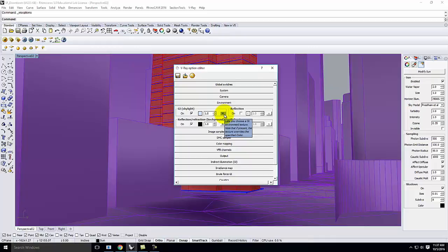And that's because there's a lot of other light that bounces off of the environment that lights the scene besides the sun. So we have the all-powerful sun shining in, but we also have reflected light off of the sky, off of the clouds, off of the trees, whatever. So we need the reflected light, and that's represented by this skylight value. That's the reflected light. What we see, or the background, the blue sky, for example, is this background value.